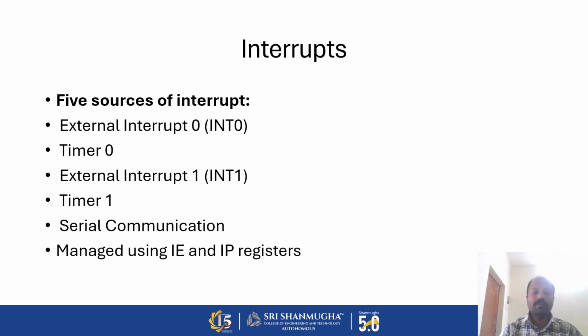These are the interrupts of the 8051. The 5 major sources of interrupts are external interrupt 0, timer 0, external interrupt 1, timer 1, and serial communication. Apart from these, reset can also be considered a major interrupt, which has the highest priority. All of these are managed using the interrupt enable and interrupt priority registers.